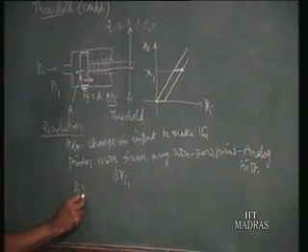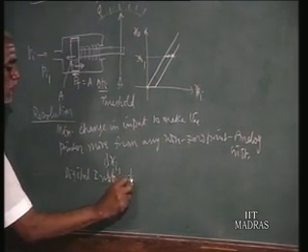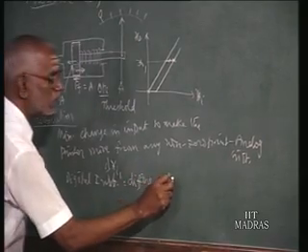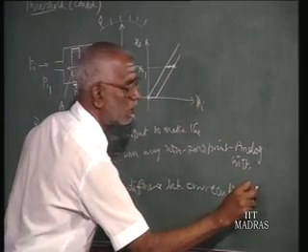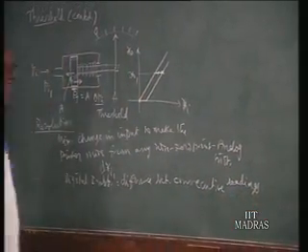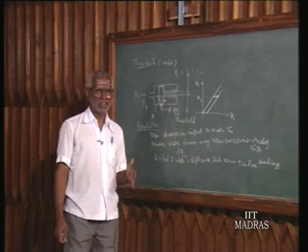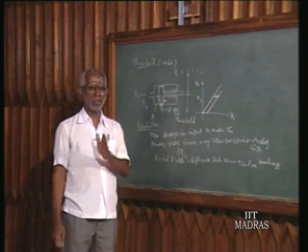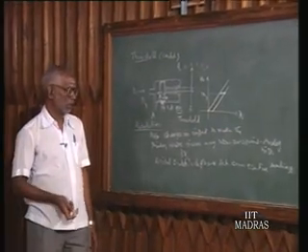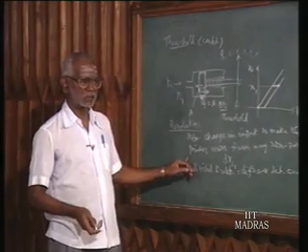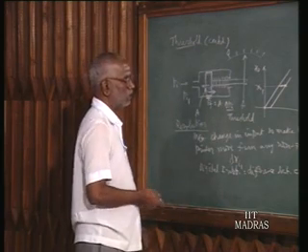Whereas for a digital instrument, the resolution is the difference between consecutive readings. For example, in a digital pressure gauge, the reading shifts from 1.1, 1.2, 1.3 and so on. So the difference between any two consecutive readings is 0.1 bar, so the resolution is 0.1 bar. That means in a digital instrument, resolution and least count are both the same. That is the property of digital instruments.